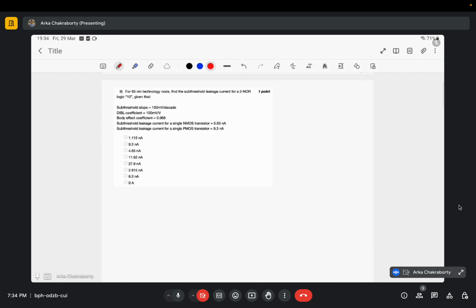So the next question is, for 65 nanometer technology node, find the subthreshold leakage current for a 2-input NOR logic with input 1 0, given that the subthreshold slope S, Debye coefficient eta, body effect coefficient K gamma, subthreshold leakage current for a single NMOS transistor, and subthreshold leakage current for a single PMOS transistor are given. So this is S, this is eta, this is K gamma. Let me draw the circuit first.